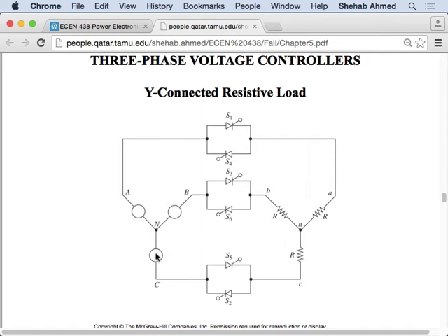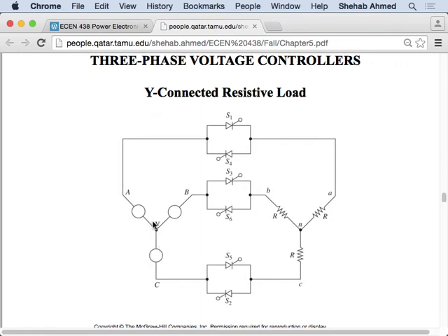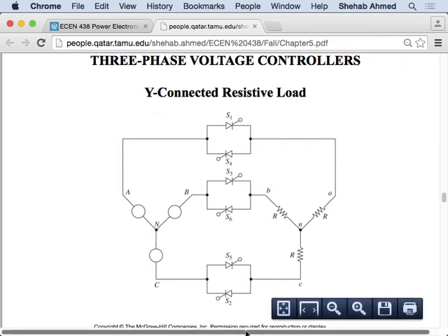So I can draw the equivalent circuit outside, like a single-phase AC voltage controller, but instead of thyristors, two diodes. Current will only go negative through phase C through diode 2 when the voltage of phase C is negative. And same thing on the other phases, right? That's where how I drew it up came from.